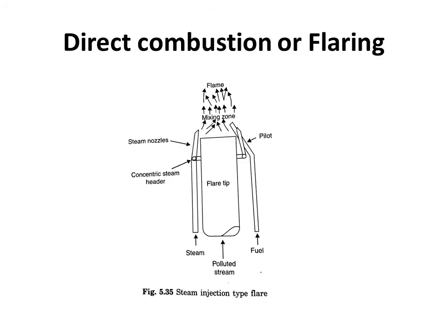The steam jets induce turbulence in the periphery of the flame and add heat to the combustion process. In addition, this sets up a water-gas reaction giving carbon monoxide and hydrogen, which help to generate a smokeless flame. A pilot flame is also provided to reignite the gas stream if flameout occurs.